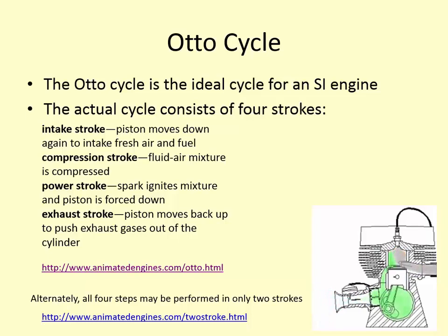Okay, so the combustion process is happening at the same time that you're exhausting the gases from it. So a lot of times you'll be exhausting unspent fuel out into the environment. The combustion process is not complete because of this. However, you get power out every other stroke. In the 4-stroke cycle, you only get 1 out of every 4 as your power stroke. Here, every other stroke is a power stroke.